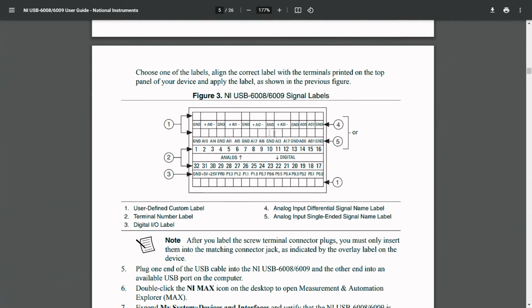So, here we can see that since it also supports analog output, we can utilize AO0 at the 14th pin and AO1 at the 15th pin, analog output channel 0 and channel 1, followed by a ground terminal. In case of utilizing it as a single ended reference, the second pin acts as analog input 0, whereas the third pin can be considered as analog input 4, analog input 1 is pin 5, and pin number 6 is analog input 5.